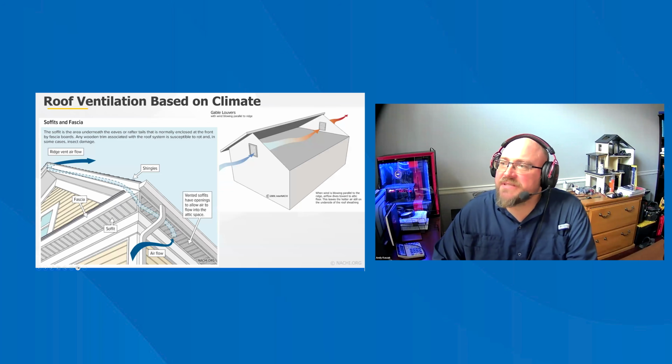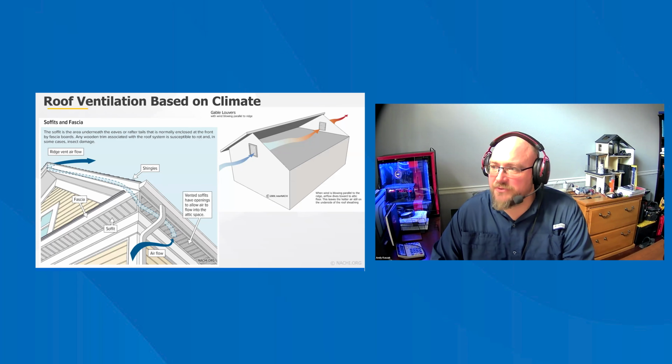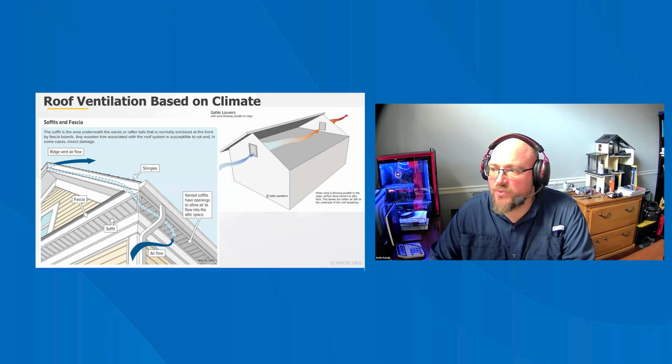A common problem with many roof designs can be found at the eaves. There is often very little space for insulation of the required thickness to be installed at the eaves without blocking the soffit vents. Often the insulation is compressed in that area in order to fit into the tight space, which diminishes its R-value. To correct the situation, some builders install a truss roof with a raised heel or oversized cantilever. This type of truss has an elevated overhang that uses a combination of soffit and eave vents with baffles and soffit dams installed at the eaves. This type of truss provides plenty of room for insulation at the wall-to-roof intersection, as well as additional window shading.